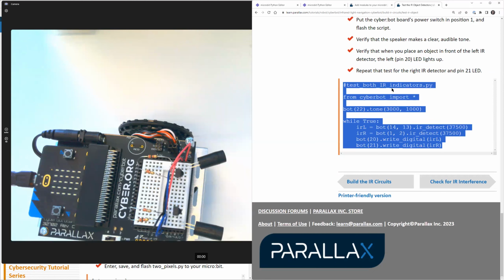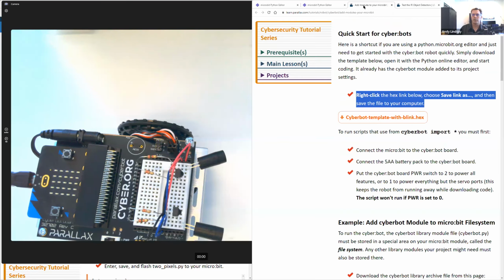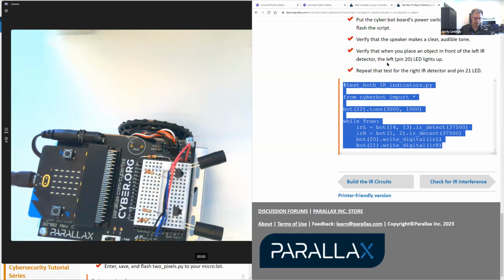Can 2 wires be in the same box in the breadboard? Well, possibly, but we usually want them each to be in their own socket. And then the trick is that rows are what connect leads together. The 5 socket rows that go crosswise on the breadboard, not the long way. That's correct. Let's see, I don't have a picture handy.